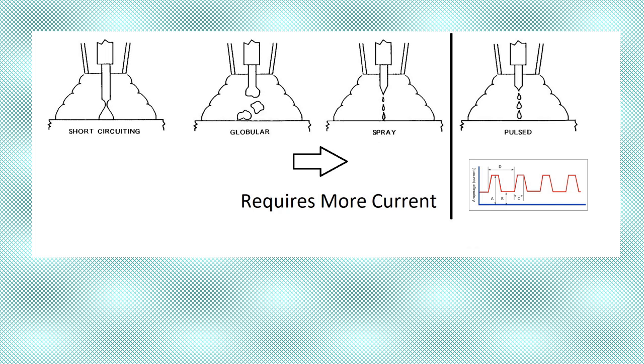So if I go over to the next one, I turn my amperage, wire feed speed, and voltage up a little. I'm going to transfer into globular. And globular, as you can see, is a little different as far as the way the liquid weld metal disassociates from the welding wire and gets deposited into the weld joint. It actually breaks up before it touches the weld base metal.